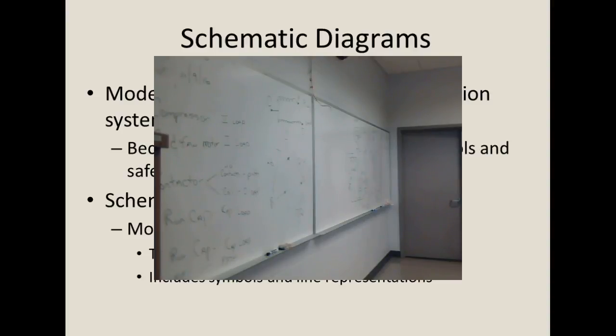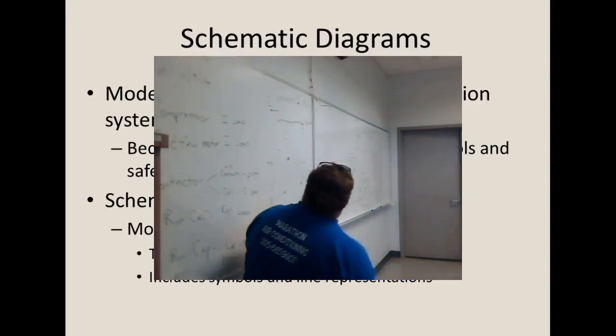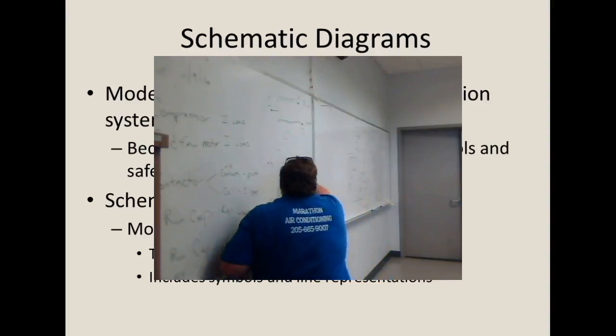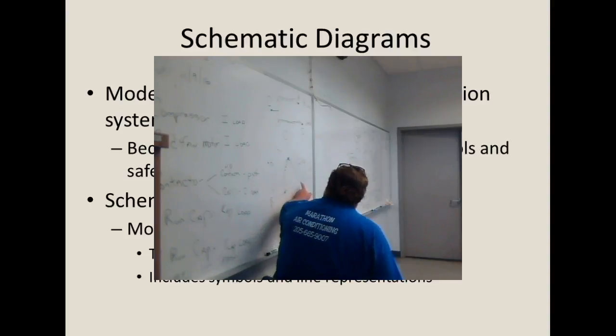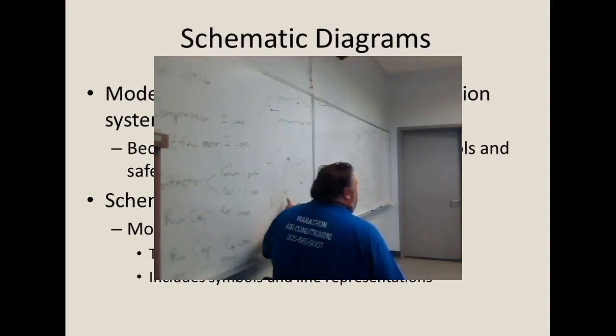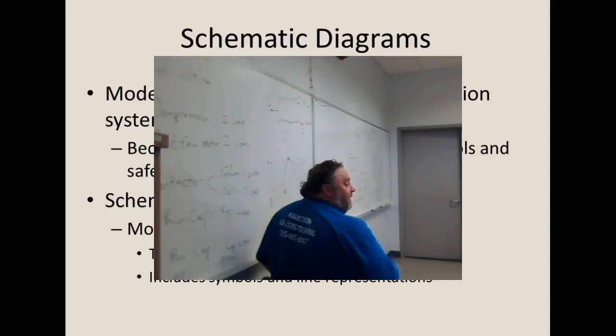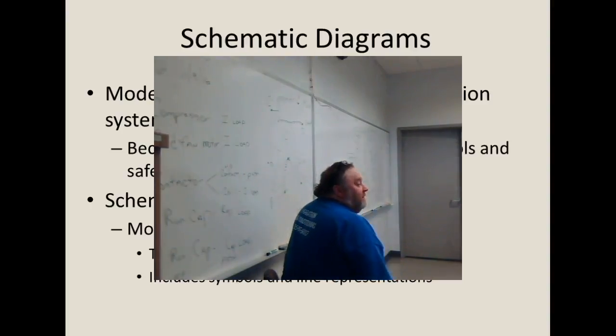Now, first of all, it says good or bad. If one of these windings inside of here, there's a winding, right? We said that was common. And you see why this is the highest, can't you? Your meter had to run through the start winding and through the run winding. It was both windings put together that gave us the 3.2. But if anywhere in here this wire is burnt open, it's going to read what? Oh well, then it's bad.